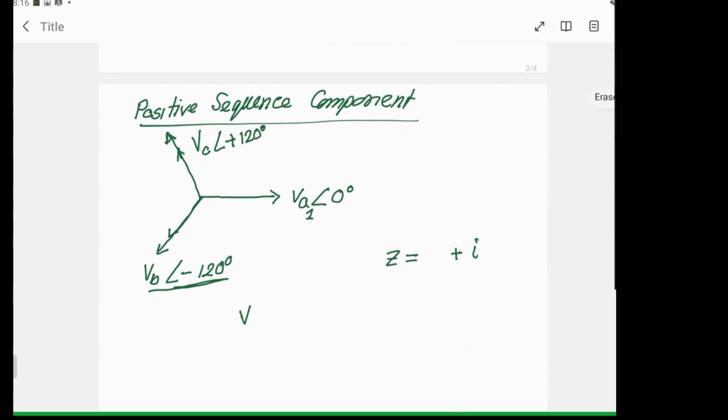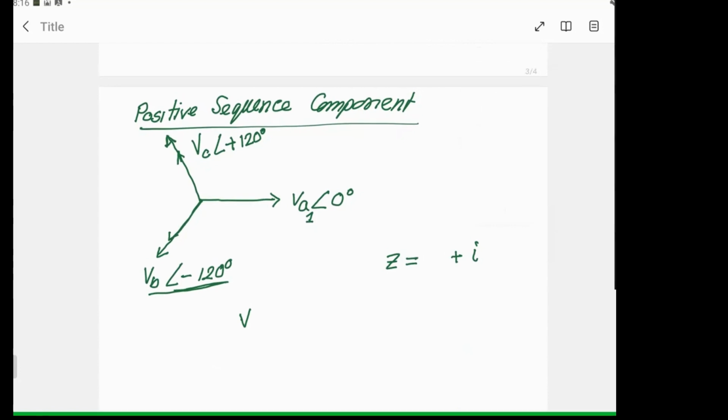R plus j XL or XC, where R is the resistance. That is how we write our impedance, right? And impedance is a vector, and that can also be written as Z making an angle of theta. So that's what we can write down, right? Rectangular or polar, remember?